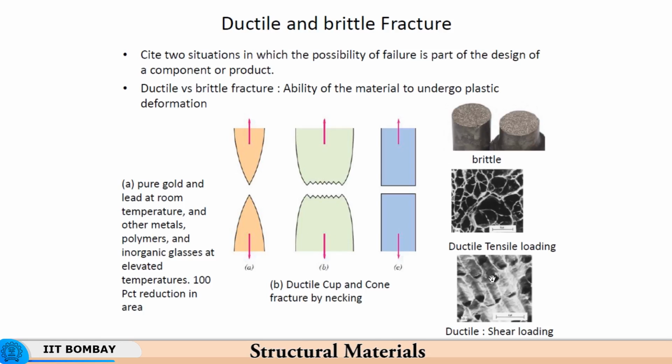Well, in this case that thinning has taken place to the extent that the material has reduced to a point and then the failure has taken place. So, these are extremely ductile materials like gold, for example, where failure would take place by reducing the cross section to a point. A point has no area as such, the area of a point is 0. So, the material continues to deform until the failure has taken place at a point.